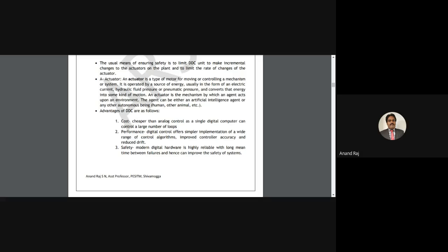So drift means... better is to, if you want to understand the drift, just go through with your analog devices. Analog devices are more prone to drift. For example, the pressure gauge, what is showing the pressure may vary with tolerance, plus or minus 5%. Whereas the digital gauge will show you the correct number, 32 psi for the pressure, 32 psi is the pressure for the tires. So if you set it digitally, the pressure set is exactly 32 psi. Whereas if you go with analog gauge, the problem would be there. You cannot fill the exact gauge of air inside the tube or tire with the help of analog devices.